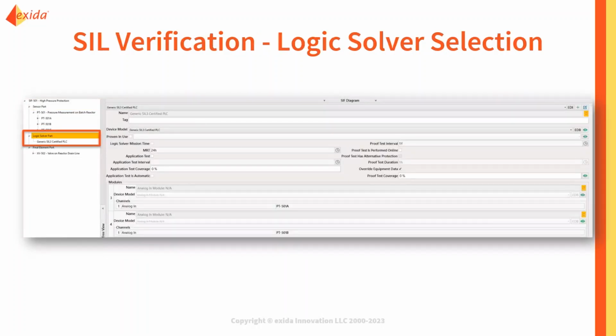Next, you can choose your logic solver. Here again, I've chosen a generic logic solver from our database, but our database has a number of options. And here you can do a proven in use justification directly for the logic solver. You can indicate if you need a logic solver specific mission time.